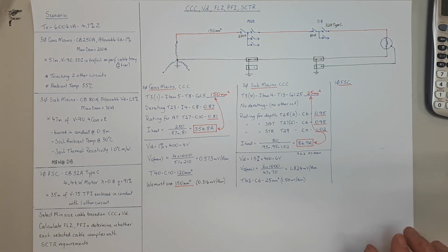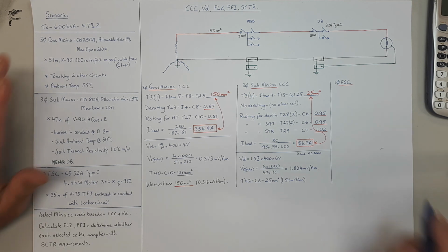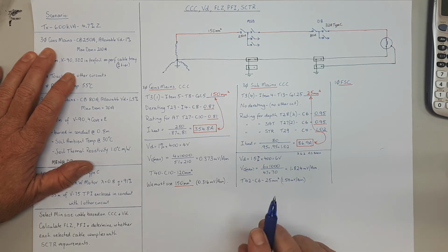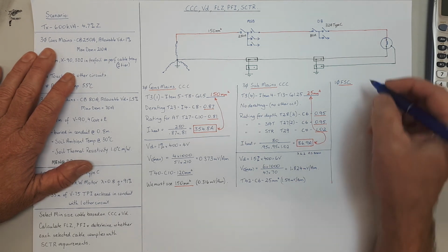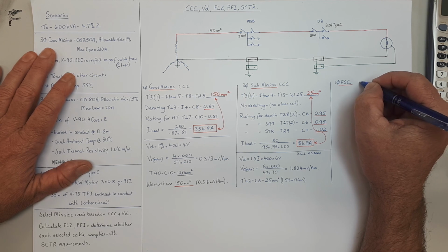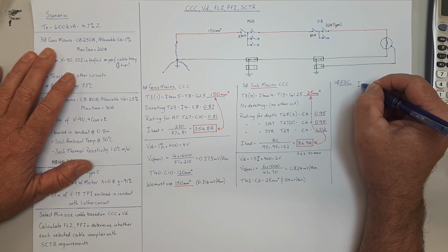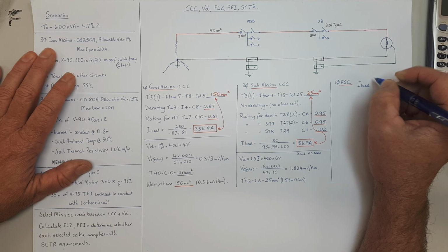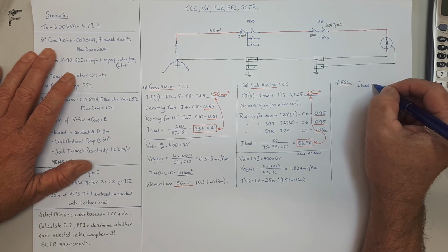We're given a circuit breaker size, but we don't know exactly what the current of the motor is going to be. So we're not given a maximum demand or a connected load, but when it comes to voltage drop, we want to use that because that'll guarantee us the smallest size cable we can get away with. So first thing we should do is work out current in the load, just as a thing to get out of the way real quick.